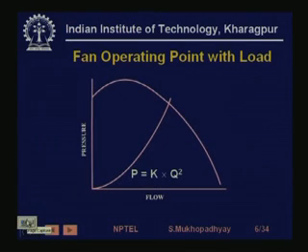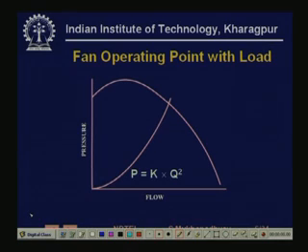Here we come back to how an operating point is established. Remember that when we computed operating points in our circuits courses, we drew what is known as a load line. A load has a certain characteristic: if you want to create a certain amount of flow through that load, in this case maybe through the furnace, you need to create a certain pressure difference.